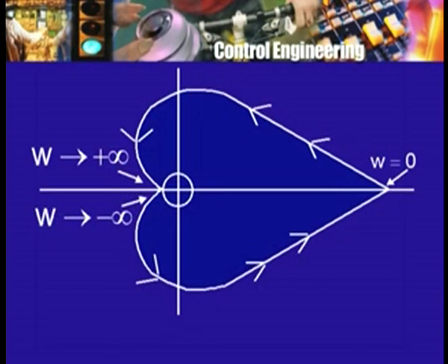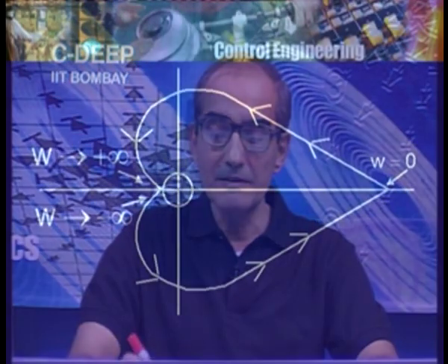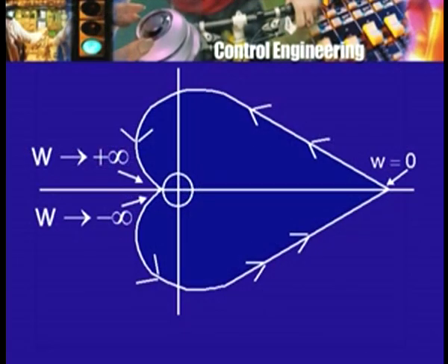So, in other words, the data that you are going to get will only consist of a number of points like this. And the angular frequency omega, of course, being 2 pi f, is necessarily only a positive number. So, here omega is only positive. Omega equal to 0 corresponds to DC, but DC is not AC. So, in fact, all of this does not hold for DC, although you can do an experiment for the DC case also, that is, apply a DC voltage at the input and measure the tachogenerator output voltage.